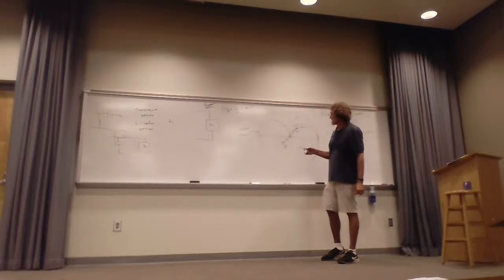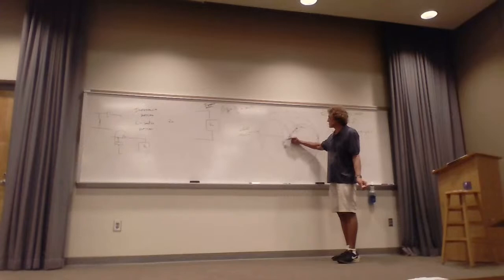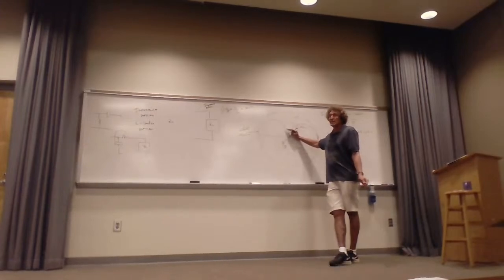So what does that mean? Well, this is admittance. I know I've got normalized admittance. The impedance of a capacitor is 1 over J omega C, right? The admittance is what? J omega C, positive J.